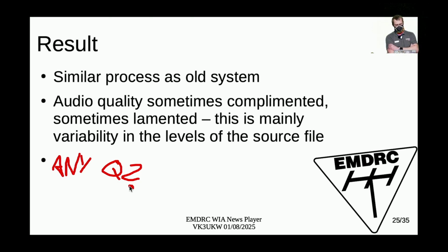There's a couple of popular programs for that. One of them is called Hamlib. One of them is called Rig Control. They basically give you a full remote control for your radio, which you can use on a computer directly plugged into the radio, or remotely. So you can set it up so that your physical amateur radio at home becomes essentially an internet radio that you can control from wherever you have an internet connection. That is something that goes back a long way.